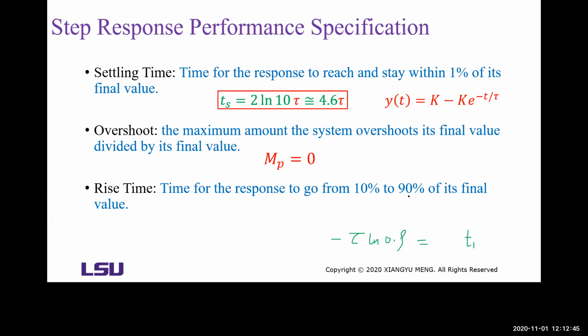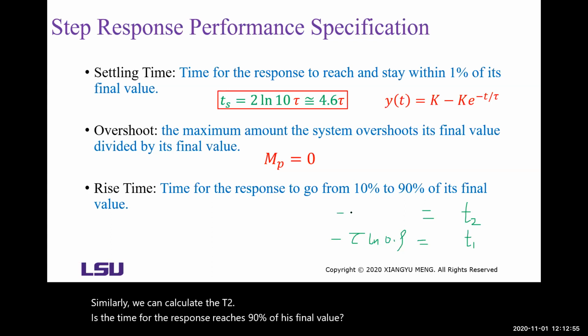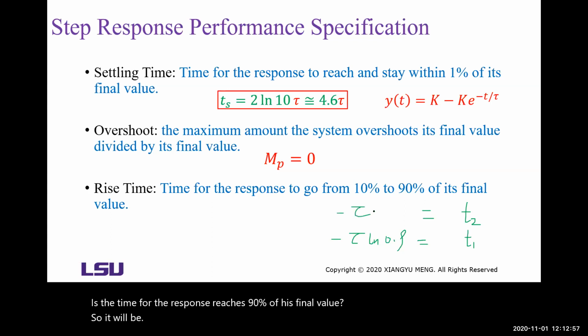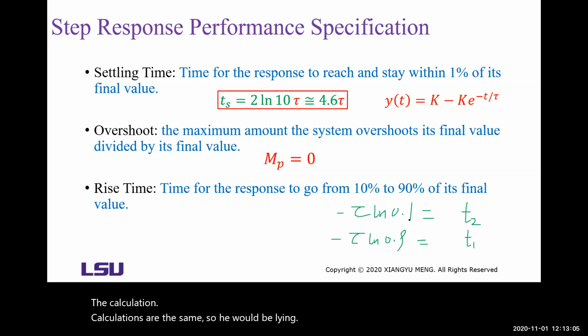Similarly, we can calculate T2, the time for the response to reach 90% of its final value. The calculations are the same, so here it will be ln 0.1.